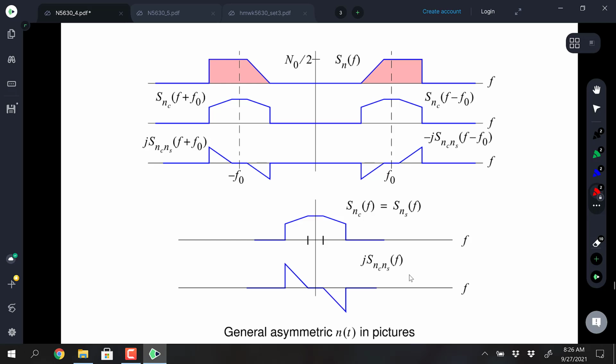So it looks like we're adding two of them together. What we're doing is taking the spectrum and then flipping it so that when they combine together, that's effectively what happens. So that's the in-phase component, and then the quadrature, the cross-spectral component, looks like the difference. So you see the little ears sticking up, positive and negative. And then if we take that down to baseband, we just have those components centered at 0 for the in-phase and quadrature, and then the cross-spectrum.